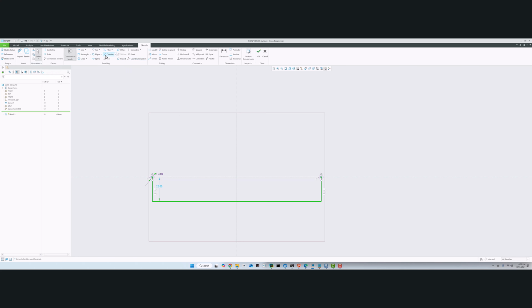And as in the drawing, I noticed they had fillets, so I'll put in a little fillet there. Whoops. I should not have had construction mode. Let me try that again. 1, 2. Let me try fillet. 1, 2. Make these equal. And this should be horizontal.